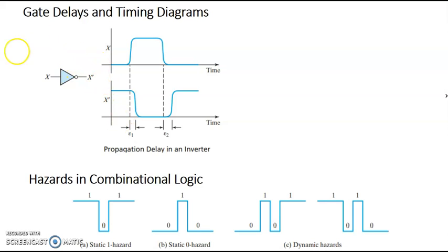We couldn't notice the time taken by the gates to process, but when we measure, we can notice it. Assume a circuit having hundreds of gates. The processing time of every gate will be added together to find the final output, so the output we get is not in line with the input. This is called gate delay.